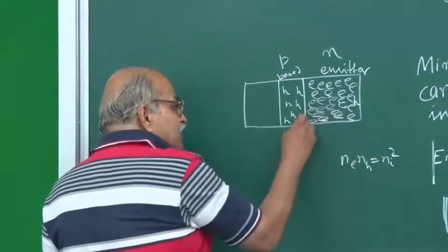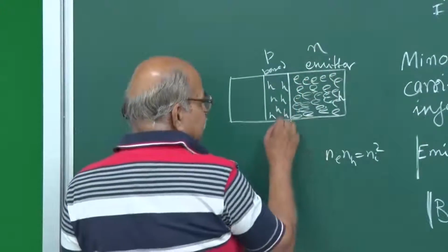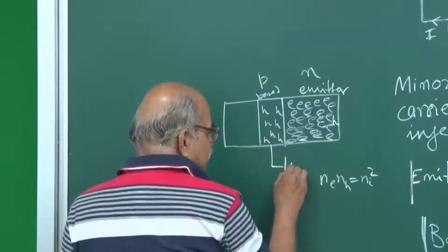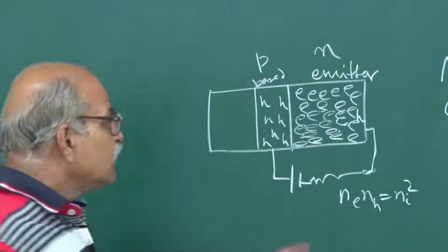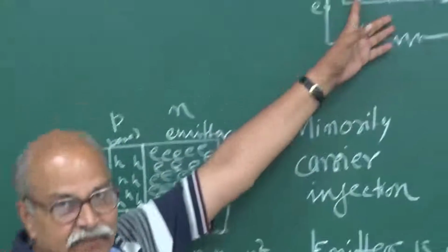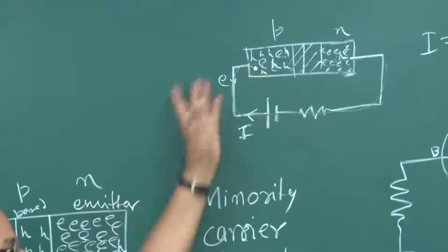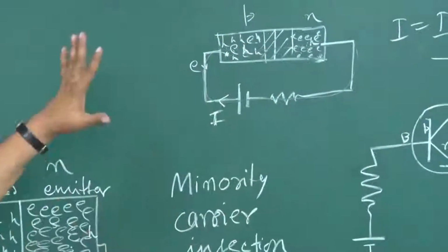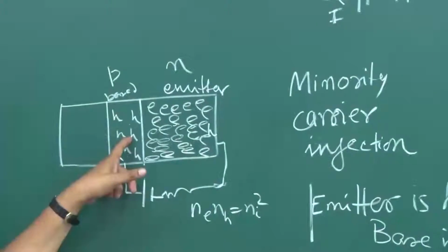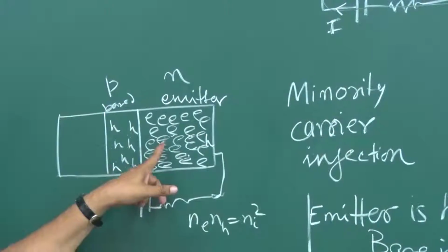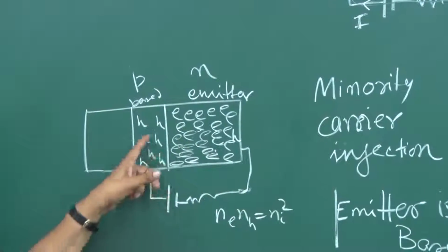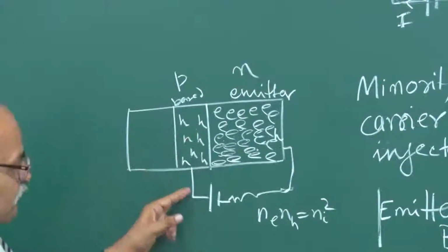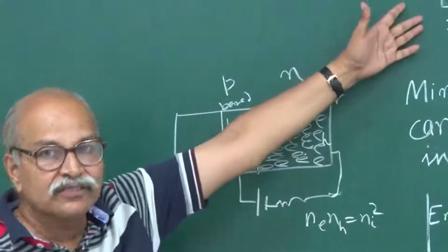If it recombines, remember this is biased, so you have this positive and this negative here. So then this mechanism will take place. The current will go like a PN junction. Whenever there is a recombination, wherever this electron comes here, and then in P region it recombines, then you do have a corresponding current, just like this.